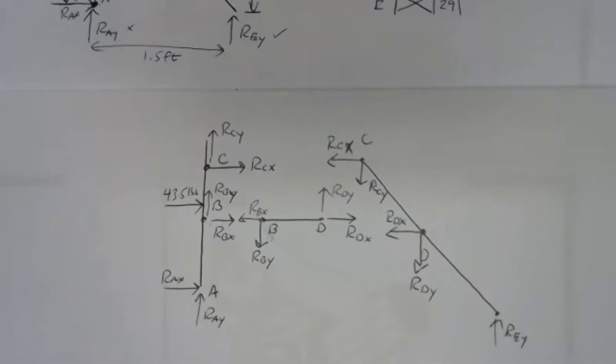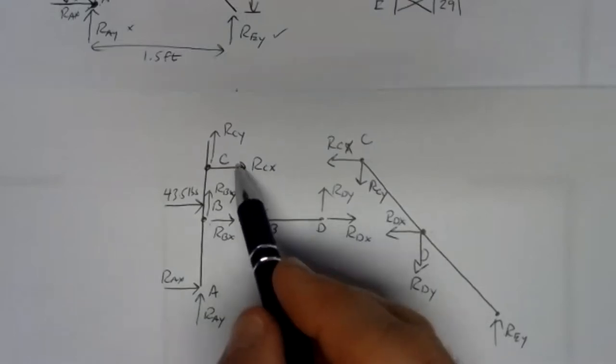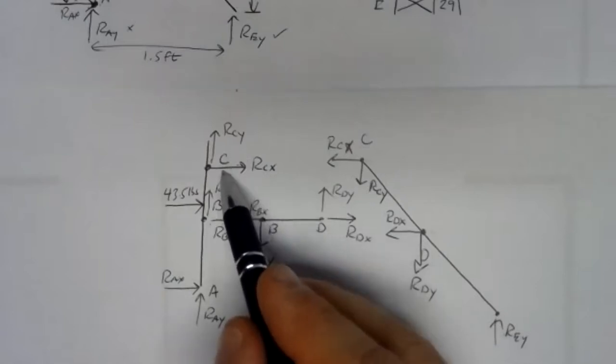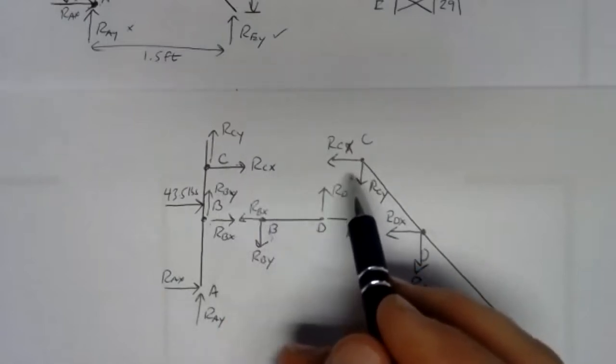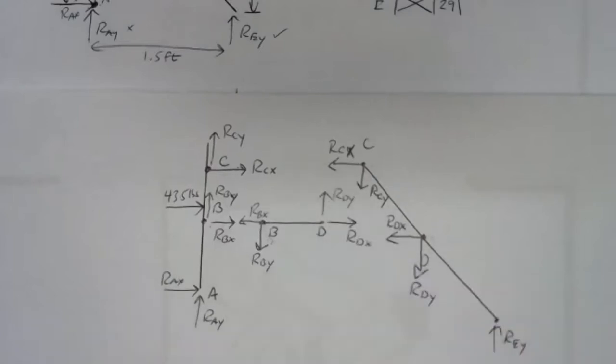The key idea is you've got to make sure these fit together. It really doesn't matter whether you assume positive or negative first. All that matters is the second time you see it, you draw the arrows in the opposite directions. We saw in the last problem that from each free body diagram we get equations. This makes sure we can use the same equations without causing sign problems.